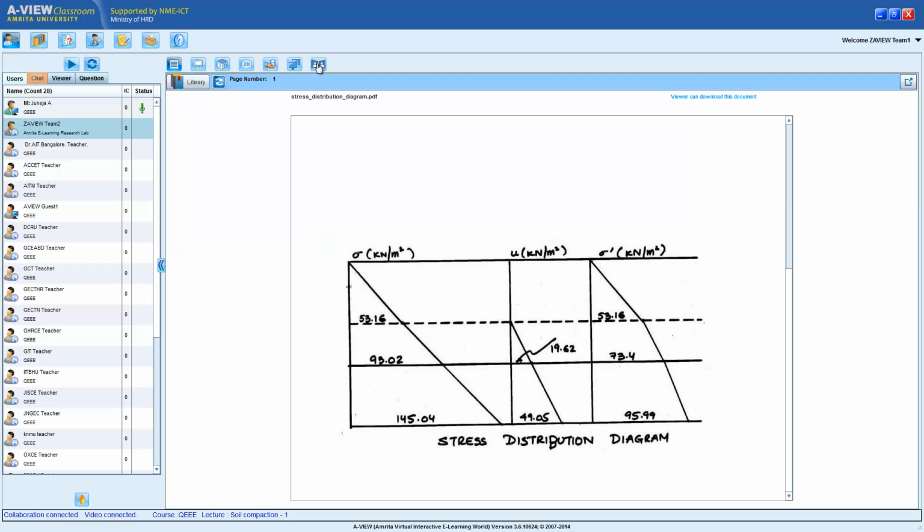This was a rather easy section. In 1 hour we looked at what is total stress and effective stress and how they are measured. We looked at how soil capillarity comes into the picture. We'll do an example of soil capillarity next time. We also looked at how the stress distribution varies top to bottom as the total stress, effective stress and the pore water pressure change. Remember, you can only measure the total stress and the pore water pressure. You can derive the effective stress, not measure it.